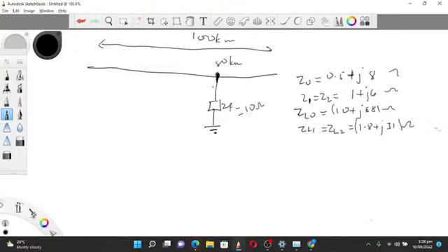So you are supposed to calculate the fault current. Like I always say, for every single line to ground fault, the fault current is just IA. It occurs at phase A, so you can just write IA is 3EA1 over Z0 plus Z1 plus Z2 plus 3ZF.